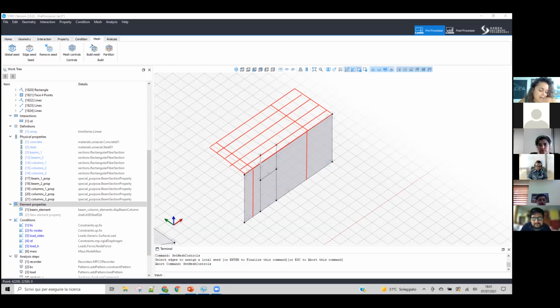To me, the best way is to do it with a hinge beam, defining different lengths for the two hinges at each side, and then define the length of your spandrel where you want it. What is going to happen here is that, for example, in this case where it's not symmetrical, it will not be positioned in the center. Where is it that you have your actual opening?